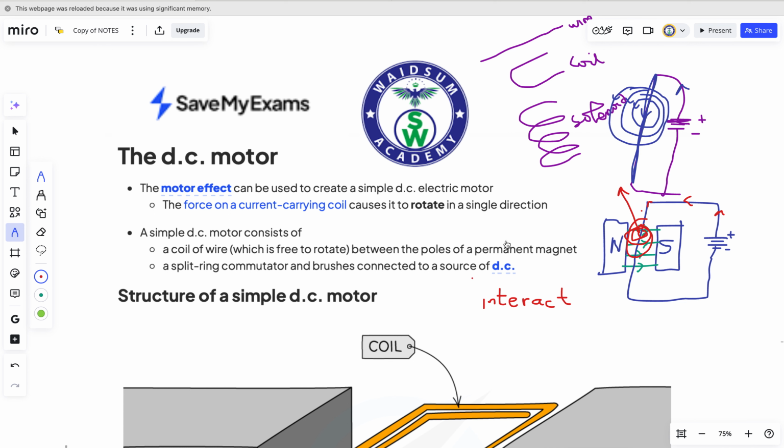Now, these are the basics to understand the electric motor. What I've just explained, if you understand it, means that you understand how the electric motor works, okay? So the first thing, like I said in an overview, is that whenever you have a conductor and a current is flowing through it, a circular magnetic field will be produced around that conductor. The second thing is that if you bring a magnet, with a north pole and a south pole, the magnetic field will be produced moving from the north pole to the south pole.